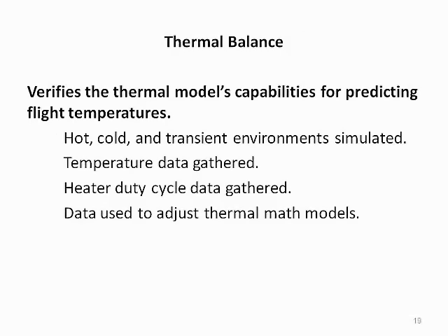Thermal balance testing is performed to verify the thermal model's capability for predicting flight temperatures. Hot, cold, and sometimes transient environments are simulated, while temperature and heater duty cycle data are gathered under steady state and, sometimes, transient conditions. The test data are then used to adjust thermal math models.